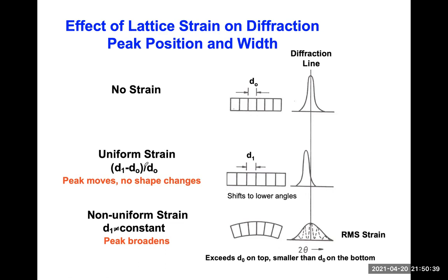The strain, which is the proportional length change as a result of tensile stress, ends up shifting the diffraction away from the angle at which we know it should occur. If there is a non-uniform strain, if it isn't uniformly applied tensile strain across the crystal, if it has some curve to it, we can change the size of the diffraction peak.